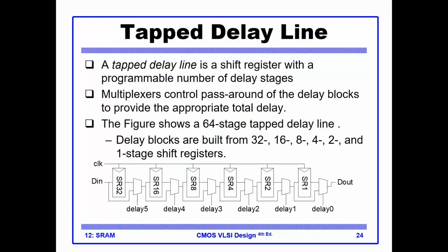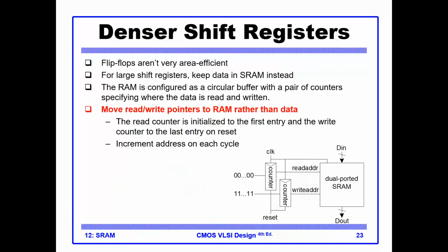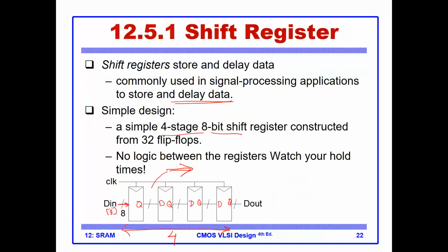Similarly here, in our shifter, in the first 3 cycles, nothing meaningful is coming out until you fill those registers with meaningful data, and then you get meaningful data coming out. And obviously, these fill cycles are typically ignored in the processing, or you assume they are zeros or some default value.